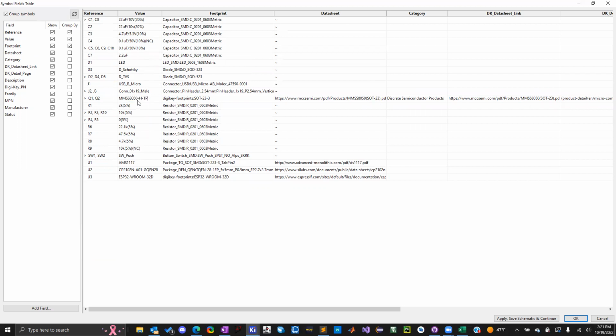I'm gonna add some extra text to this value for the transistors. We're gonna pick the exact transistors that the real dev kits use, which are J3Y transistors. You guys don't have to include that, but I'm gonna include that, and I'll show you why later, when we get to the bill of materials, because we're gonna do a BOM for this one, and I'll show you the ordering process. Hopefully by then I will have approved funds so I can order everything.